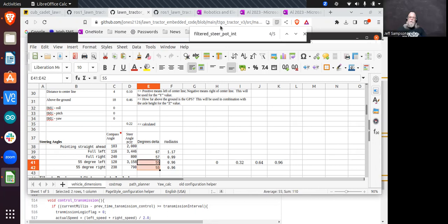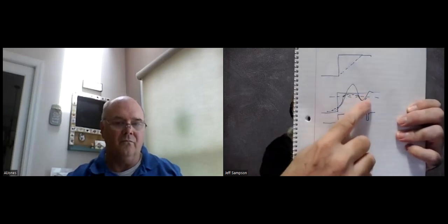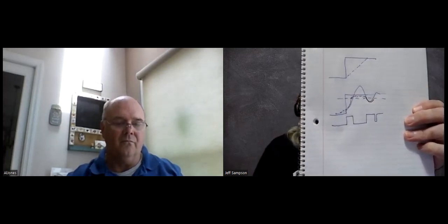But I'm talking about two different things here. There you're saying you're going to limit back at ROS what angles this can go to. What you really need to do is have your vehicle know: do not go beyond this point. That's why, as I say, after you've done all your calculations and figured out the power value, just before you output your PWM, check your position. And if it goes too far, kill the motor at that point. If you rely on limiting the actual angles coming in, I don't think that's going to do it for you, because once you pass it into the PID, it's going to try to oscillate back and forth, and when it does, it's going to go further than you want it to.